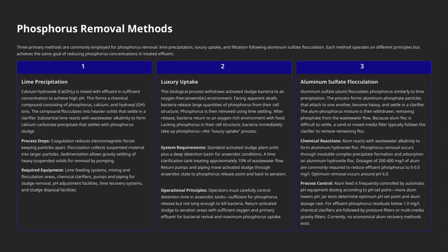To control this process, alum dosage is often automated based on pH readings, with pH control being critical for optimal removal. Typical alum dosages range from 200 to 400 milligrams per liter, aiming to bring phosphorus levels down to very low concentrations. Currently, there are no cost-effective ways to recover alum, so it's used as a chemical additive without recovery options. In summary, these methods, chemical, biological, and combined chemical-biological, are all vital tools in our arsenal to meet water quality standards by effectively removing phosphorus.